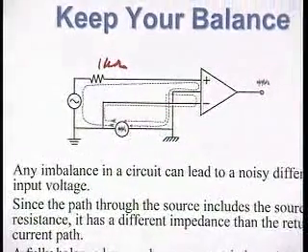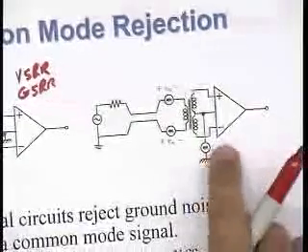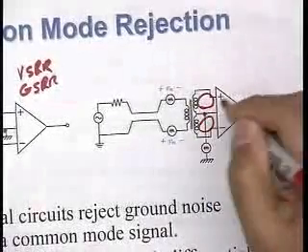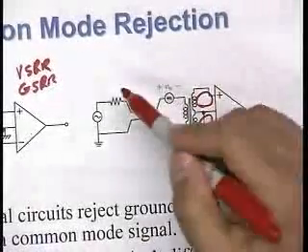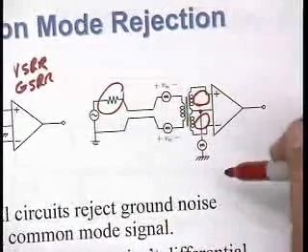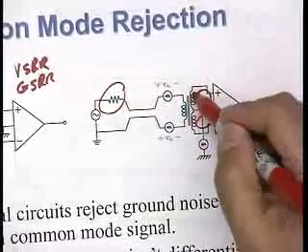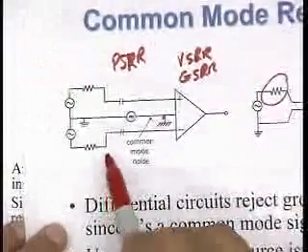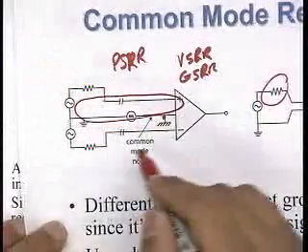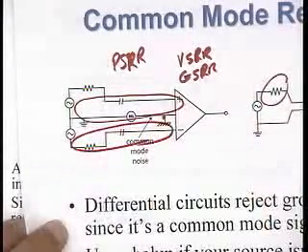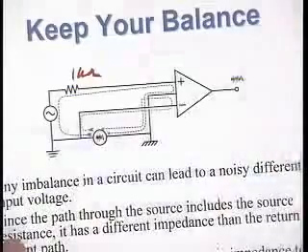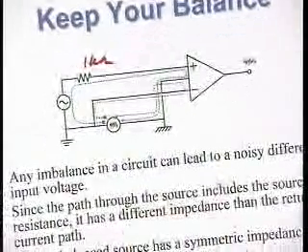That's why I use this circuit, because now in either direction, this direction and this direction, I see the same impedance. I take the single-ended source and create a differential resistance. I create a differential source. And so now I'm equivalent to this picture, and the noise induced on this loop is the same as the noise induced on this loop. Okay? Questions or comments?